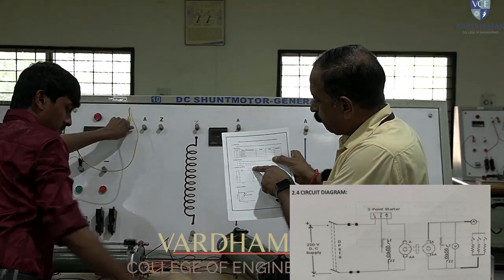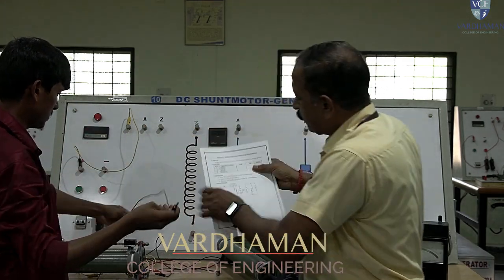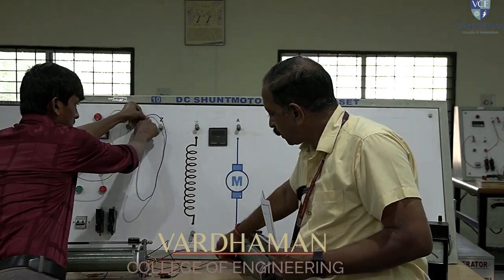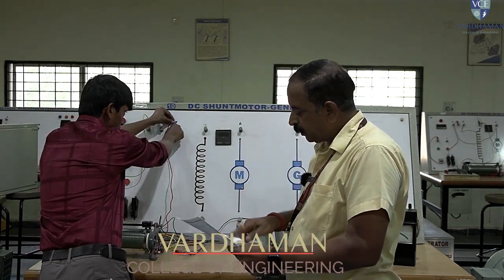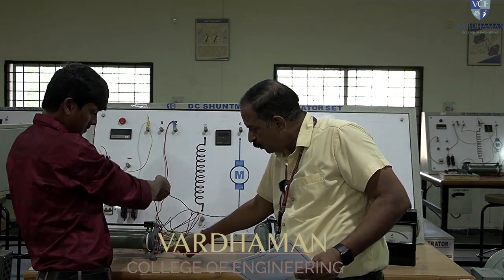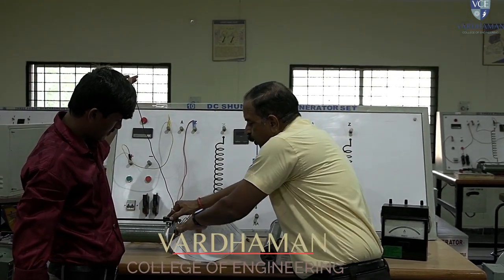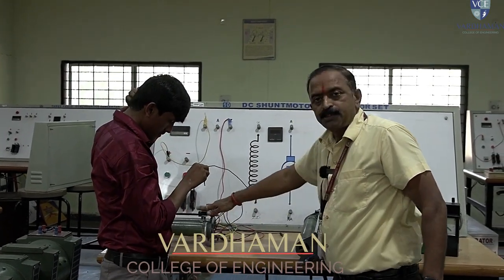Next, coming to the magnetic field coil Z, there is a Z on the starter, and it is connected to one terminal of the rheostat. So take the 400 ohm, 1.7 amp rheostat, and one terminal is already connected. So Z is taken to the rheostat, and there are two terminals on the other side. This position indicates that if it is near the terminals, it is 0, and if it is away from the terminals, it is maximum. So now the resistance point is 0. If you keep this knob at the initial position near these two terminals, it is the 0 position.